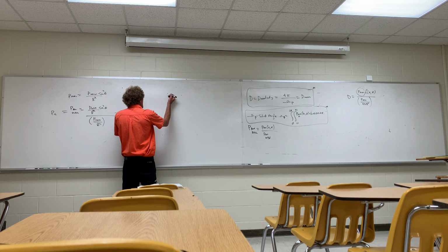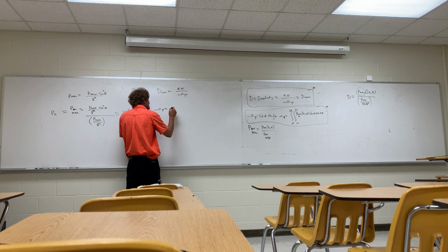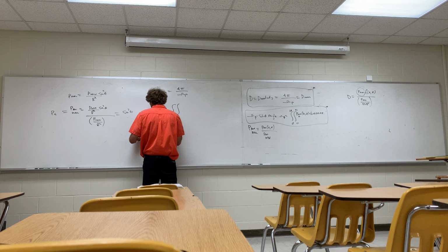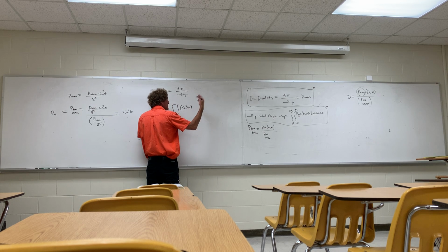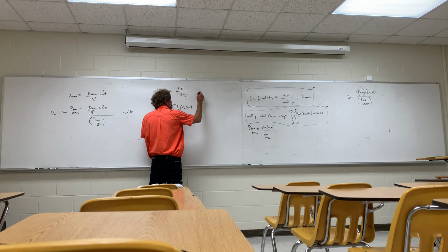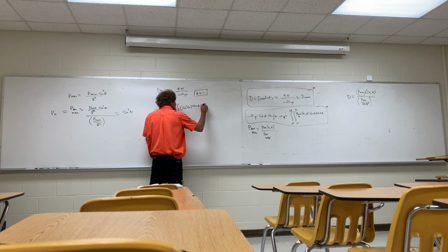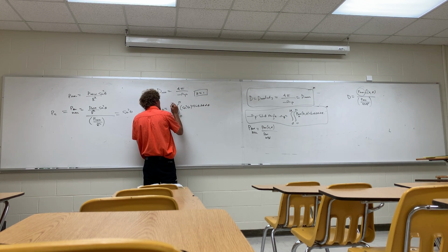So now, I want to get directivity D max, and that's equal to 4 pi over omega p, and omega p is equal to the integral of the normalized power density, which is sine squared theta, times, and he calls it the differential solid angle, but you can say it's the differential surface assuming R equals 1. And it's sine of theta d theta d phi. Well, theta will go from 0 to pi, and phi will go from 0 to 2 pi.